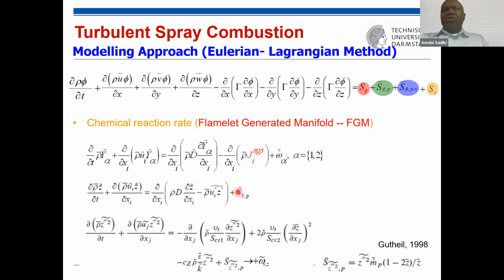So normally for single phase, it is a conservative quantity without the source term here. But now it is no more a conservative quantity, and the source term introduces the effect of the evaporation, which changes the composition and the mixture of the gas phase, so that we have a source term, and this source term is important and makes the difference between single phase combustion and two-phase combustion at this point.